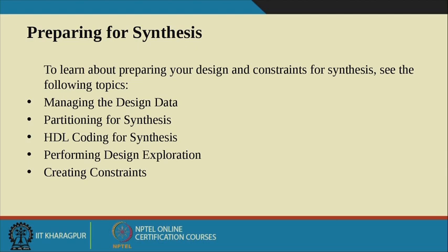For preparing your design or the constraint file for the synthesis, you have to manage the design data, do partitioning for synthesis, do good HDL coding for synthesis, perform the design exploration, and create the constraint file. In parallel to that you have to do the functional simulation too, which is not part of this, but you have to do the logic, that means functional simulation of your circuit, also. So I said, okay, managing the design data.